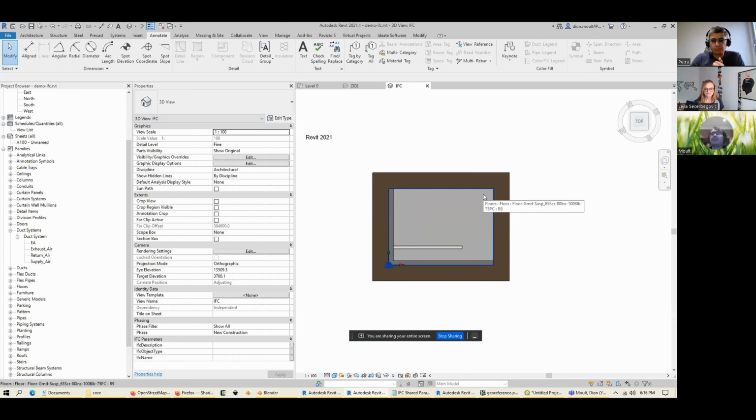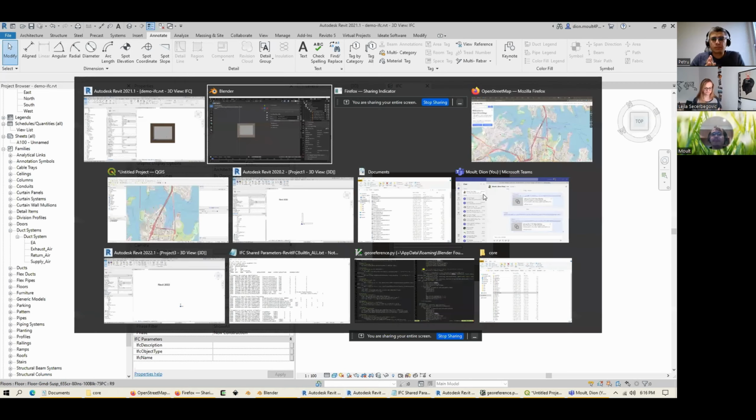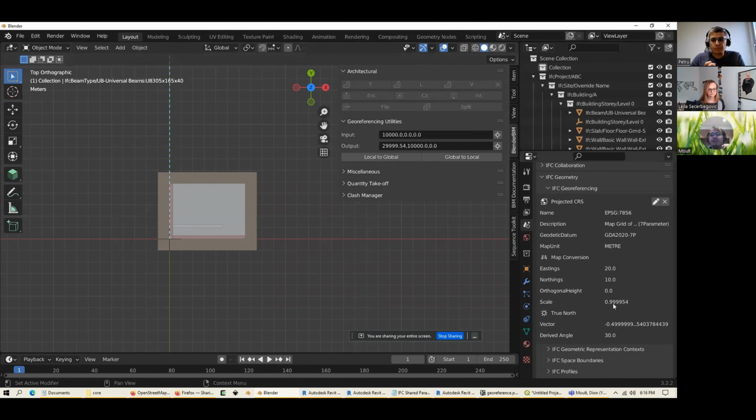But there's another reason why this is important. It's important for people to at least realize, sure, if you just want to put your blinkers on and use the survey spot coordinate tool and get it roughly correct, that's fine. But at least if you record this, there's a clear definition of the coordinate system that's being used. Is this a local system, or is this one-to-one, the eastings and northings like they would do on a civil project? And just the ability to record that precisely and take it down by the surveyor is, in my opinion, a very valuable thing to do.